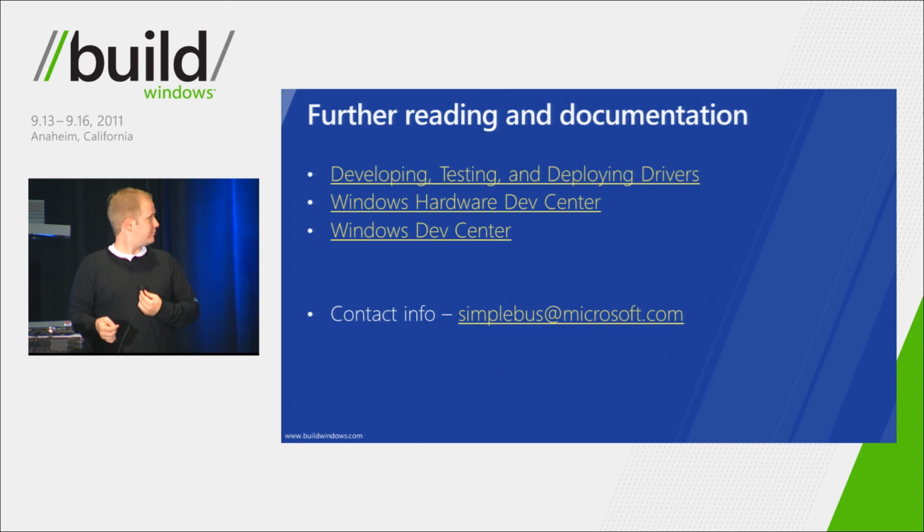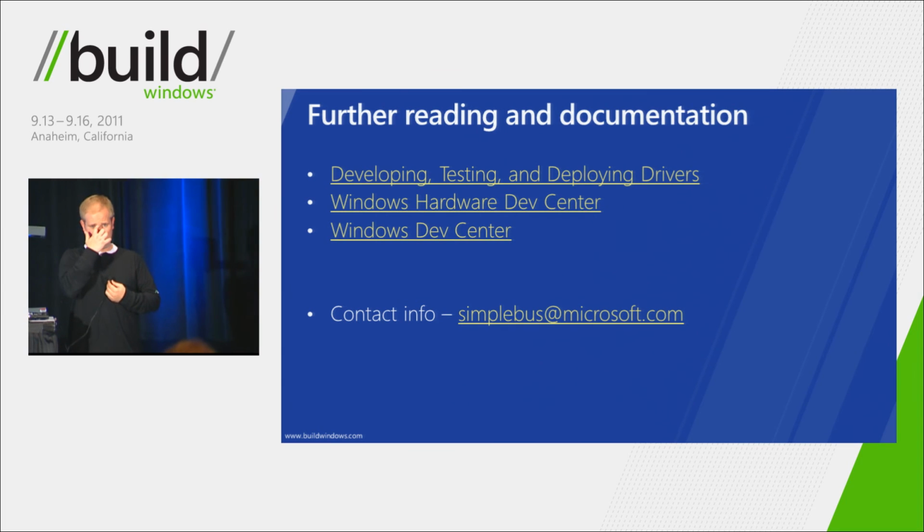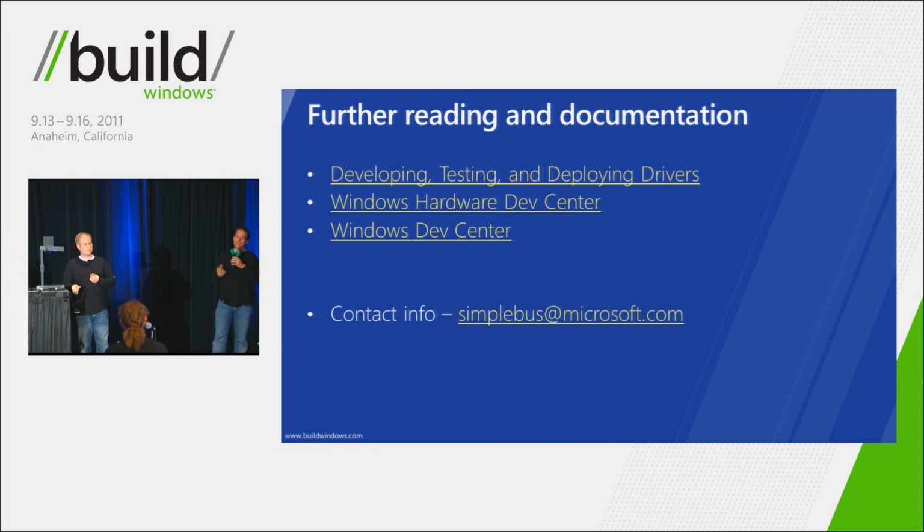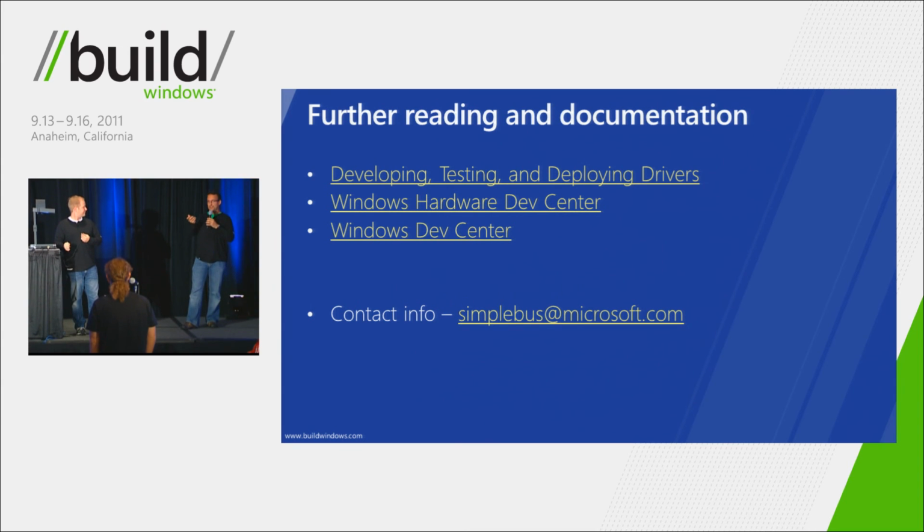Yeah, SDIO can also provide power within the bus, so we have a more direct parent-child relationship that we have to maintain for power management. But basically, if you can slap ACPI on the node and add resources into it, then those resources can be used by the resource hub. So as long as it's something in the device tree that you're happy to describe in the system firmware, you can do that. I don't think you would use GPIO and SDIO for a plug-in card anyway. It seems a little weird to have an extra line.